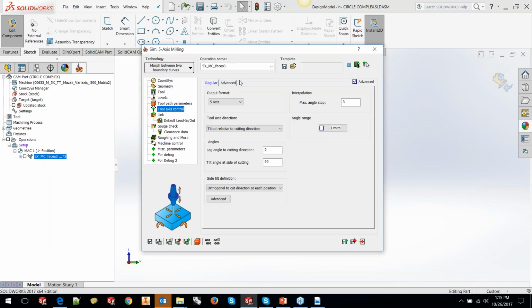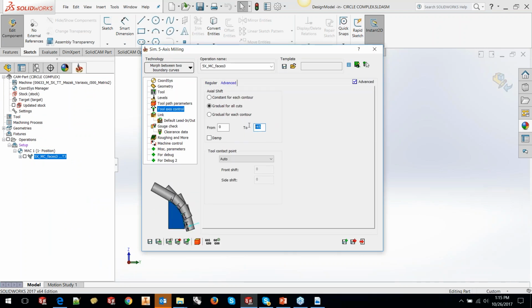So what it is actually doing is distributing this 45 millimeter cut length over the entire surface, so that the same point that cut on the top is not cutting the next pass. The next pass is shifted up by some amount so that it distributes that 45 millimeters over the entire surface. Shimshon, I will try it with a barrel tool, but not here online, and I'll let you know if it really does. I think it should still do the same thing because the functionality is the same.